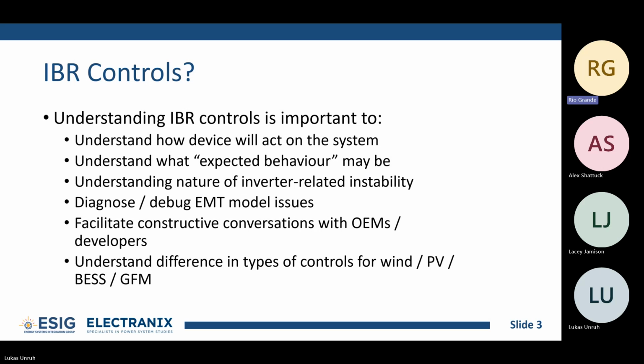And it's very helpful when you're diagnosing and debugging EMT model issues to understand how they are supposed to work. If you want to talk the same language with the OEMs, the experts who are actually supplying this equipment, then it's also very helpful to facilitate those discussions. It's also helpful in understanding the differences in the types of controls when you're talking about wind, PV, battery, and grid following versus grid forming.